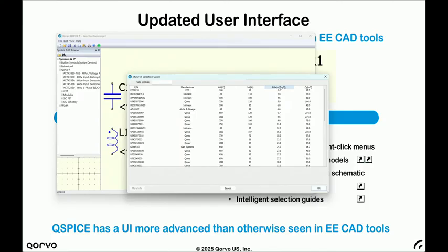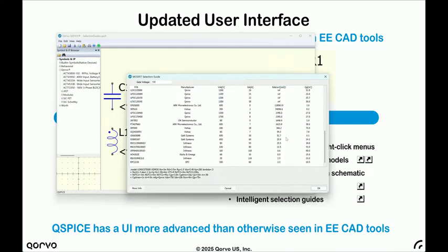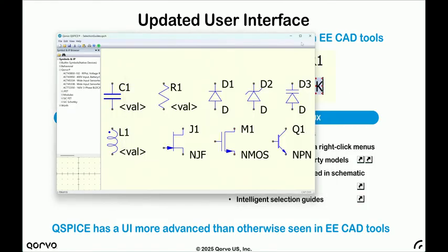But what you'd like to be able to do is say what voltage you're going to run it at. It might be even a different voltage yet, and have it just compute the RDS on. So that happens. Say you want to run it at 4.8 volts. You say the gate voltage here, 4.8. You see, a lot of them are infinite because they're not enhanced yet, and you can sort them by the voltage. And that's possible because the same person that wrote the device equations wrote the selection guide. So it has stuff like that in it for intelligent selection guides.